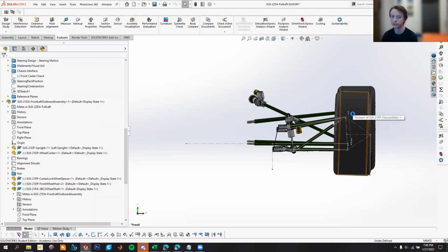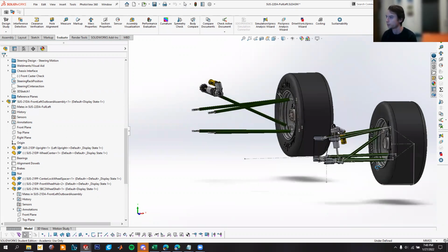And it's characteristics like that that create this bump steer effect, because the tire at the bottom is still going to flatten out when it contacts the road, and it's going to induce a force which is going to want to steer the car in this case in the left direction. So the tire would want to turn outwards to flatten out its bottom part.